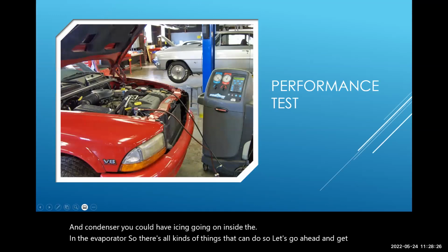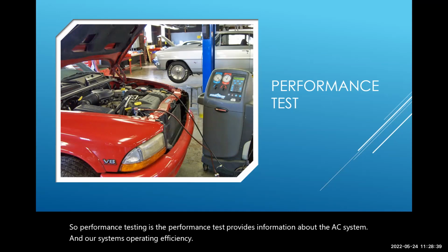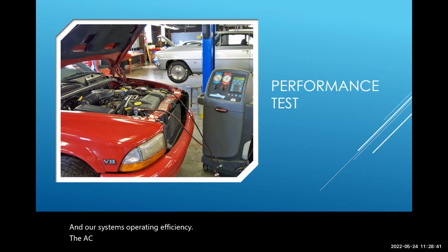So performance testing is, the performance test provides information about the AC system's operating efficiency. The AC system high side and low side pressures are measured, and the discharge temperature of the passenger compartment is measured.